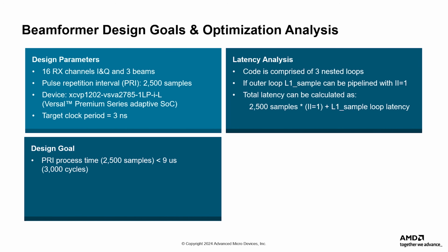Therefore, in this loop, each iteration must be able to execute in the very next clock cycle after the previous iteration. So, the strategy for achieving the specified performance will be to apply a pipeline II equals 1 pragma to loop 1 and then ensure that the HLS synthesizer is able to meet the requested initiation interval.